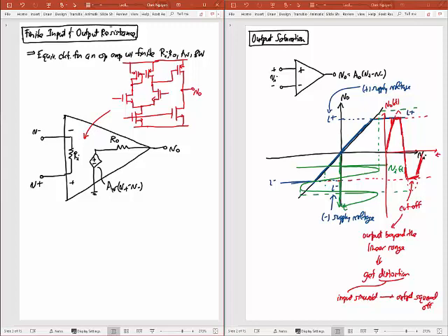And if I have a plus and minus terminal, I can identify my plus and minus terminals with this design here. And I got a power supply, VDD, VSS, right? You're already working with power supplies with your op-amp in your lab today, but you're not working with the innards. This is what it looks like inside. There's no resistor or anything in there. There's no voltage-controlled voltage source. There's just a bunch of transistors, and they implement this.